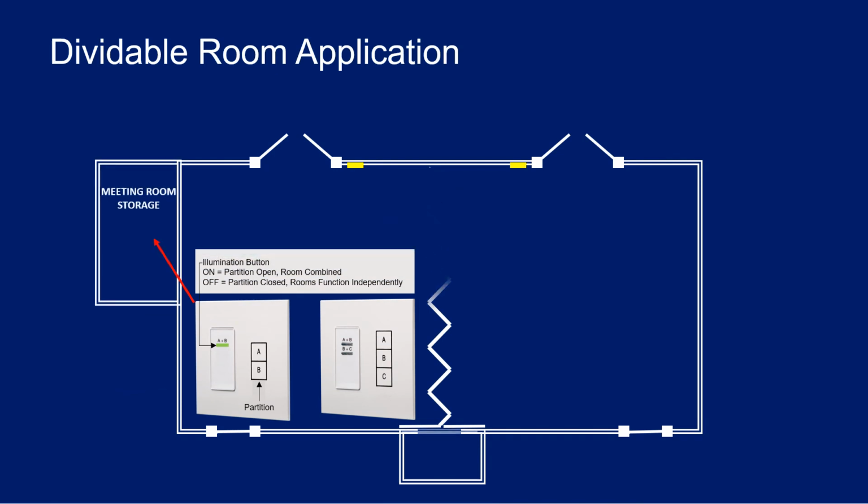The room combined station is usually located adjacent to a dividable meeting space in the storage room where you might keep extra banquet tables, chairs, or supplies. When the air wall is engaged, the push button on the station is in the off position and should not be illuminated. This allows each touchscreen to control the lighting in its own segment of the divided meeting room.